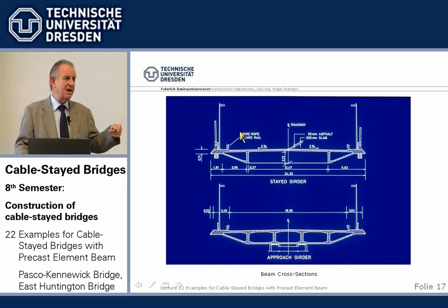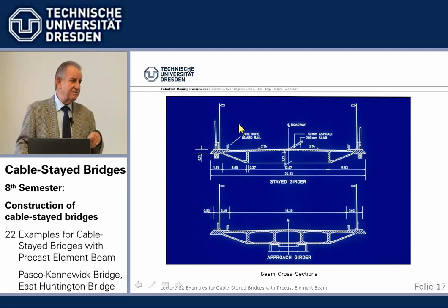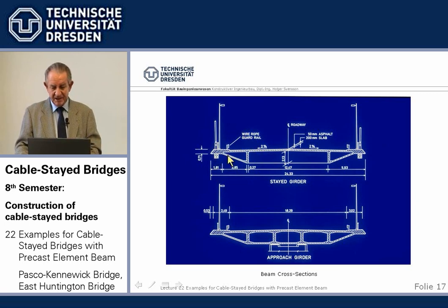You remember Helgeland, we later went to 1 in 350, but this was one step there. And we have here these outsides aerodynamically shaped, but there is no bottom slab because it is not required, and it was always an idea of Leonhardt that you could do it without bottom slab, no box section here. It worked. It's not ideal. You have a little problem here at these points to get the stresses okay, but it works.